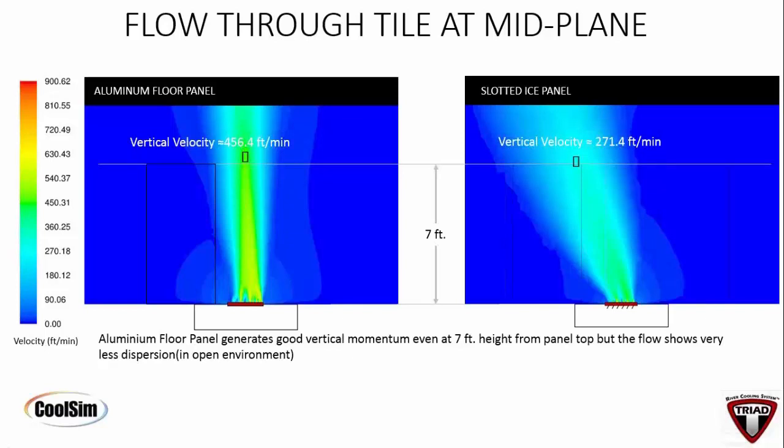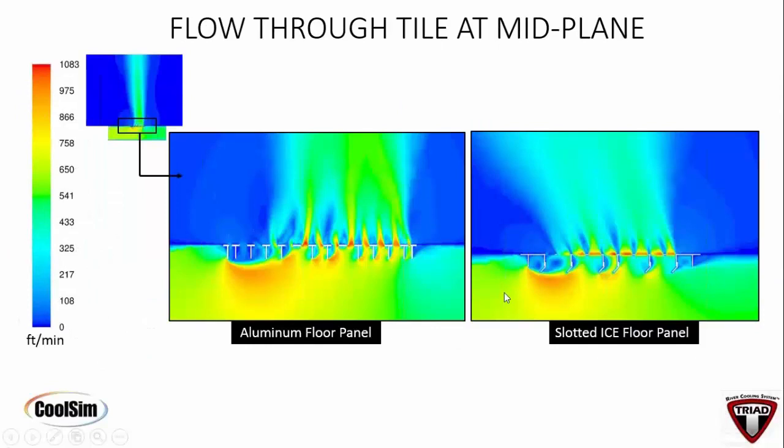What is the angle range for the slots in the tiles? If you look at our ice tiles, we use varying sizes of orifices, hole openings, intentionally, and so the angle is actually being driven by the anterior fin, and it creates a throw. I think that's what Paul showed in one of his slides. It was 18% or something like that. Yes. I think that answers the question.